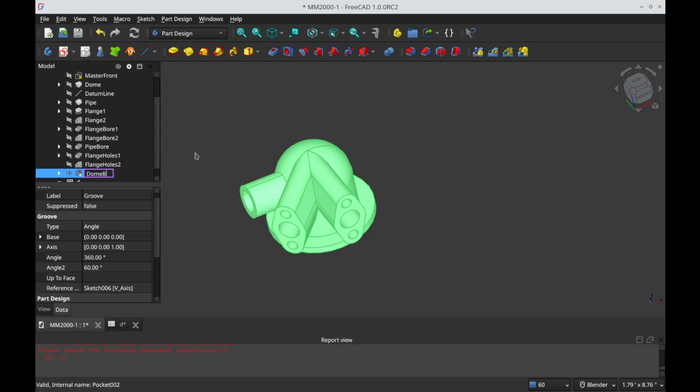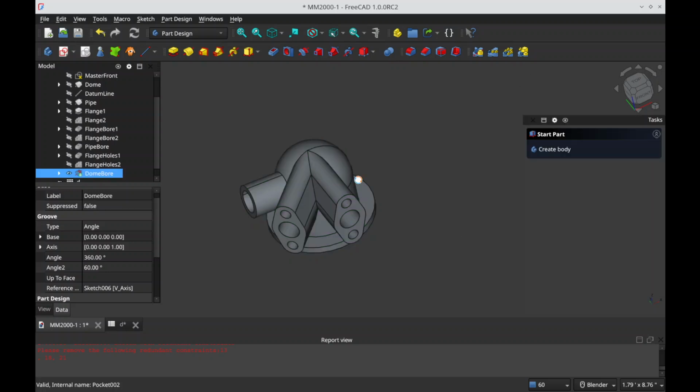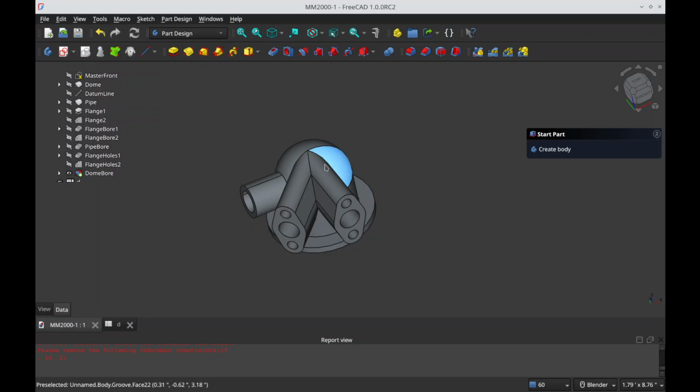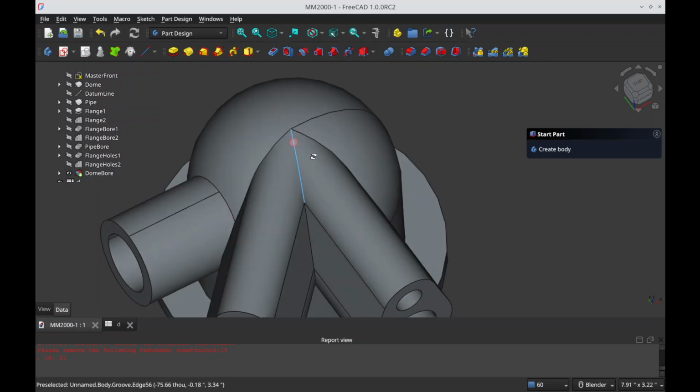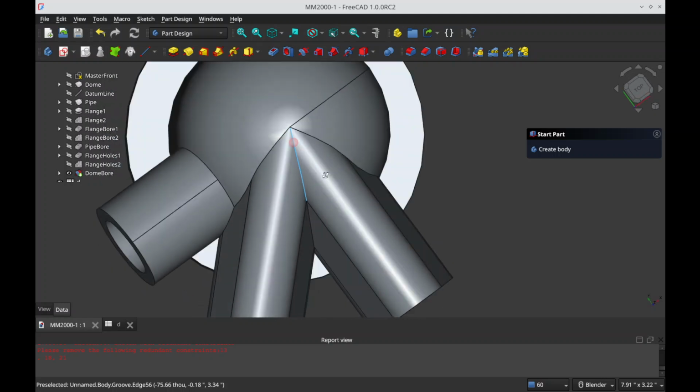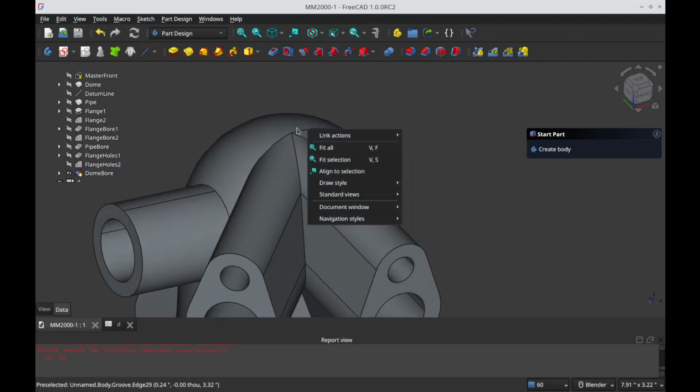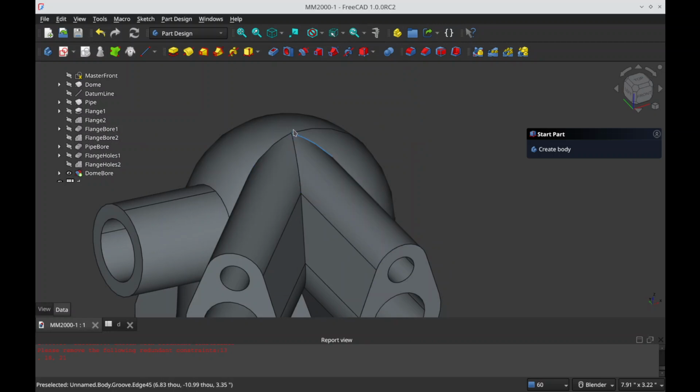this is dome bore. To get the fillets to work, and I don't know exactly how to apply this more generally, but you can add a flat up here, a little circular flat bit, and that is just going to, again, break up some of these faces so that you don't have a combination of 4 faces all at the same point. So let's at least give that a shot.